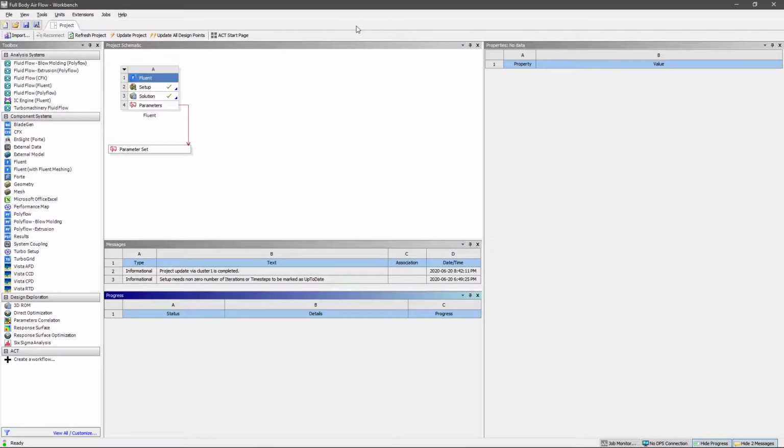Alright, so this tutorial will go over how to import or set up the CFD-Post module, how to open CFD-Post, the mesh entities that will be present and which ones you'll deal with, the coordinate system, setting up turbulent kinetic energy contours, pressure contours, wall shear contours, pressure coefficient contours, as well as media export settings specifically for images and the settings that I've best found and views that are important for your team to look at.